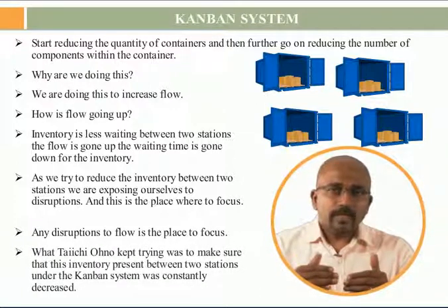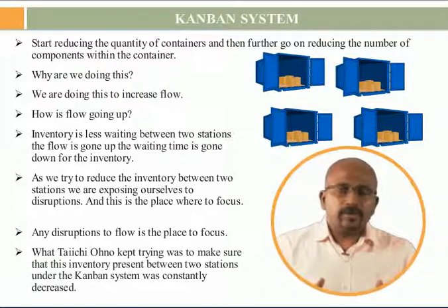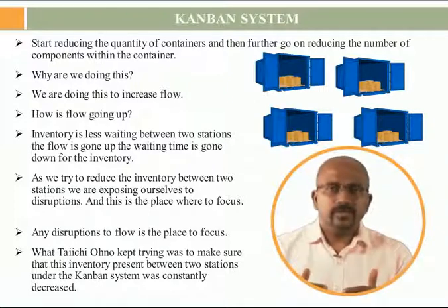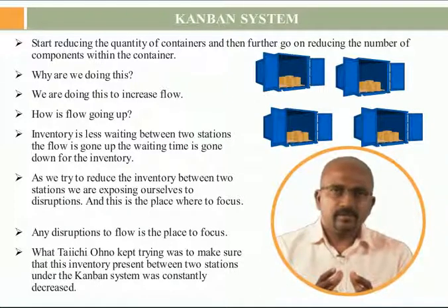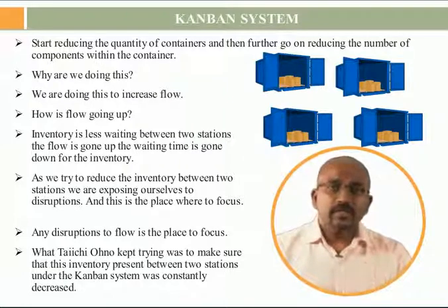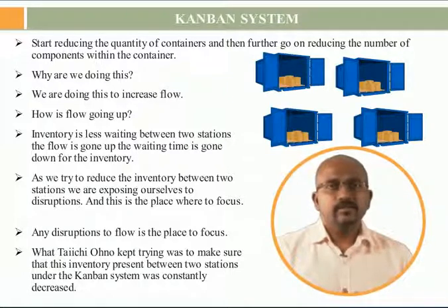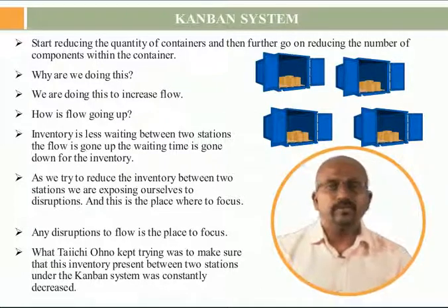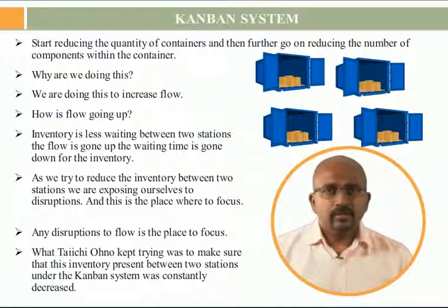What Taiichi Ohno kept trying was to make sure that the inventory present between two stations under the Kanban system was constantly decreased. But in trying to do that, you are forcing multiple setup changes on equipment which is not dedicated or which has to produce multiple components. And in trying to do that, you are fighting a Herculean task of setup changes.